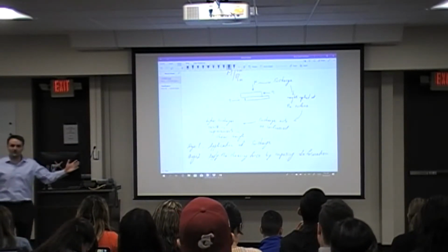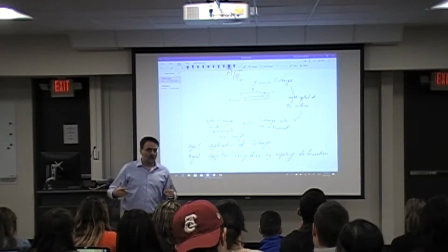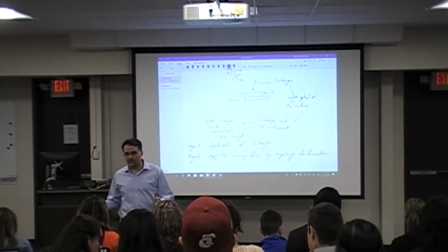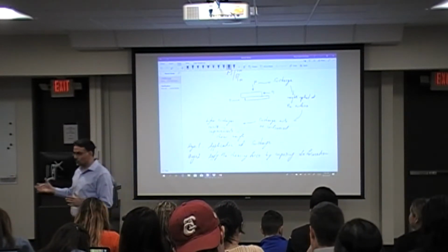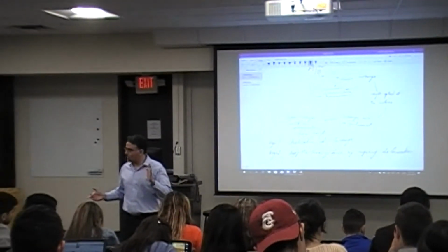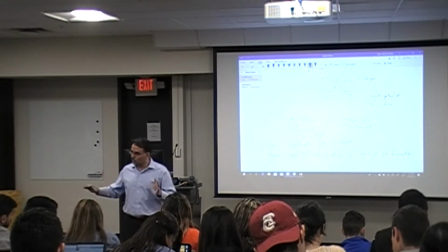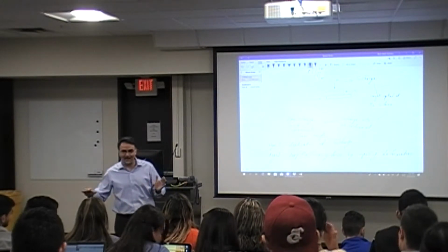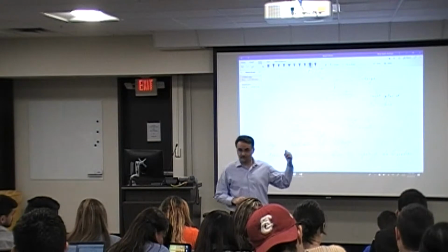All right, tell me how you calculate the normal stress. Let's go one step back. What is the objective? The objective is to find the C value and phi value, right? For that, I'm looking at my Mohr-Coulomb failure envelope. What do I have on the y-axis? Tau, right? What do I have on the x-axis? Normal stress, right? Or horizontal axis, we have the normal stresses. So what is my normal stress?